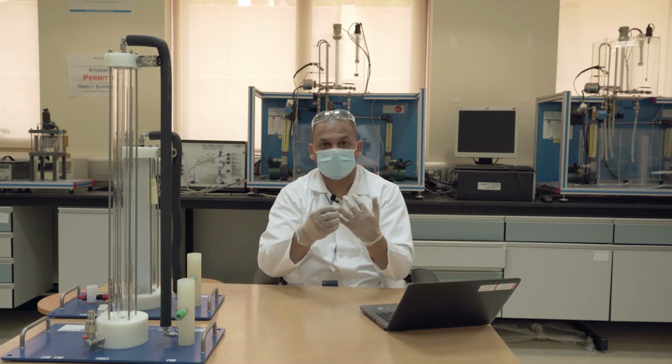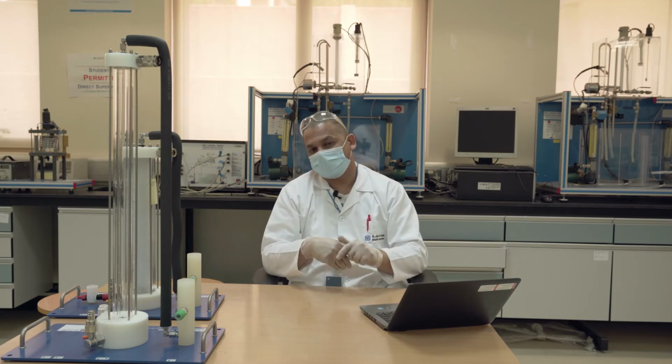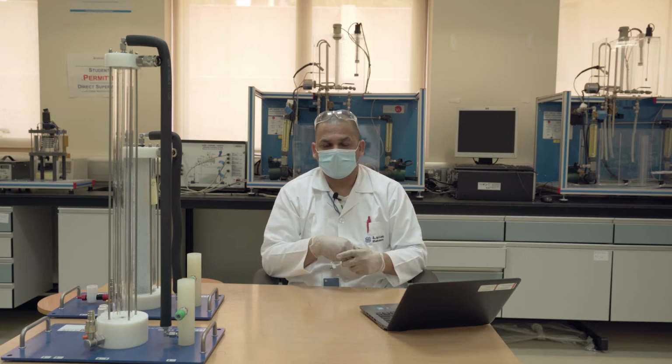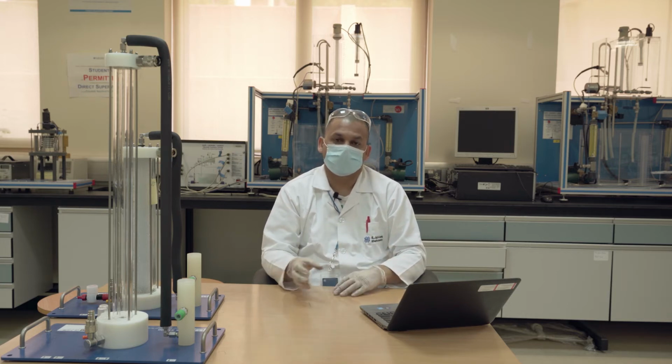This experiment is well known, and values are available in the literature, so that's why we have chosen this one. Now to achieve the kinetics, in the lab we have 5 different types of reactors: a batch reactor, a CSTR, a plug flow reactor, a laminar flow reactor, and a plug flow reactor with packing. The question I need to ask is, do I need 5 reactors? The answer is no. But why are we trying to learn all 5? Because I, as a student and as a professional, when I want to design an experiment, can choose which to use for what purpose.